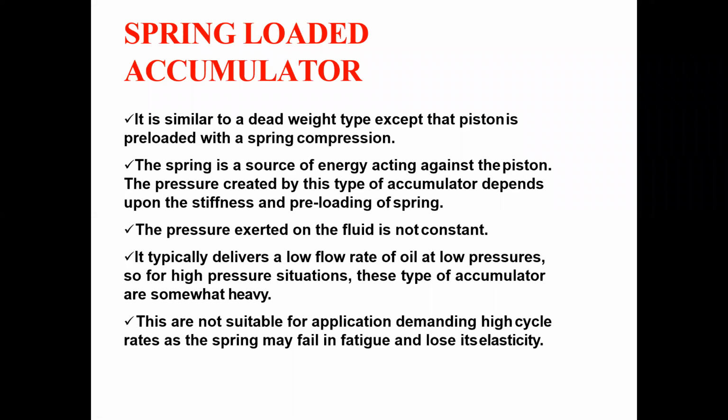These are not suitable for applications demanding high cycle rates, as the spring may fail in fatigue and lose its elasticity. The life of the spring-loaded accumulator is less as compared to the gravity accumulator, because the spring can undergo deformation due to multiple times loading and unloading.